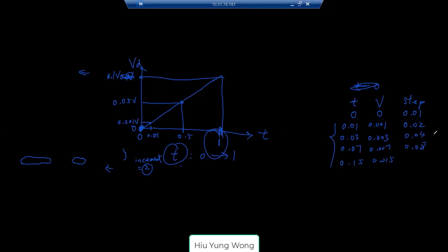Right? Now, let's say I'm too aggressive. Maybe you say, hey, 0.05, now the step is too large. It cannot converge. Or it is struggling. It almost failed convergence. Then maybe now, let's say it does not converge. Then say, oh, I better cut back. Okay, this failed. Then let me cut it. I am going to have a decrement equals to 2, right? You can tweak this parameter.